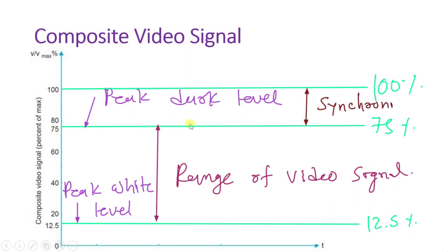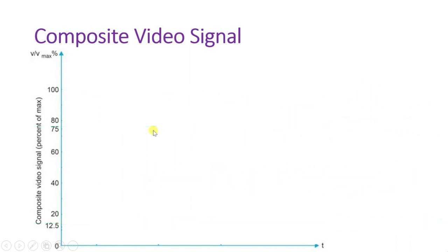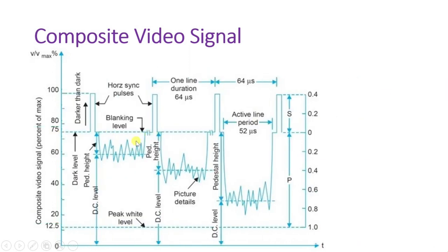Sync pulse amplitude: of the 140 IRE units, 40, or close to 29%, are for synchronization. All sync pulses have the same amplitude, namely 29% of the video signal peak-to-peak. Figure 7.5. Oscilloscope image of two composite video signal lines with IRE amplitude scale. Note the 140 unit IRE scale on the left.